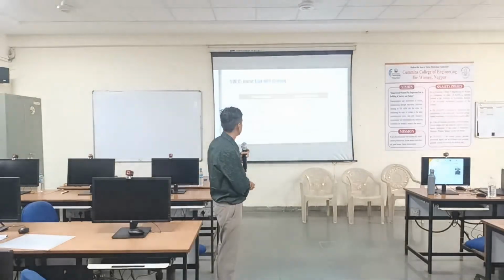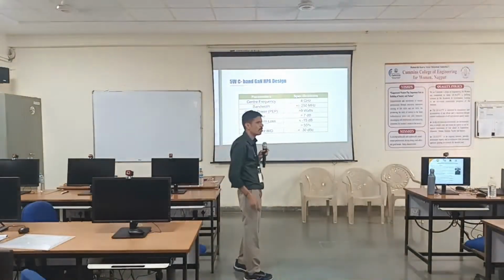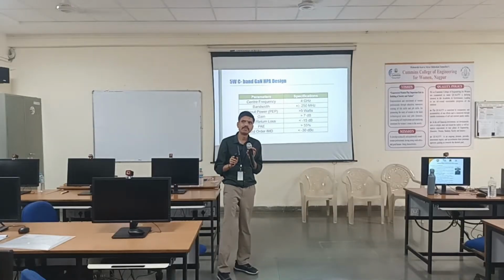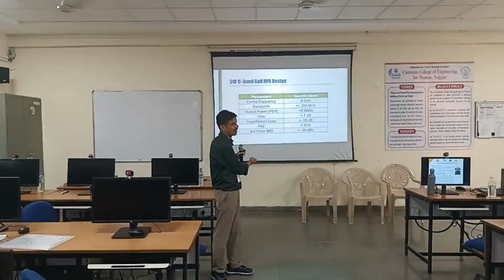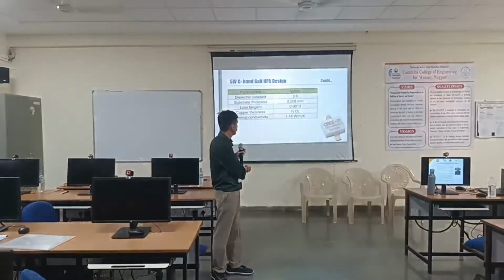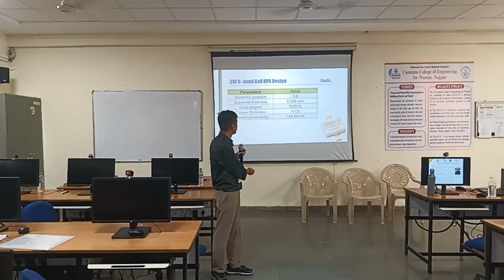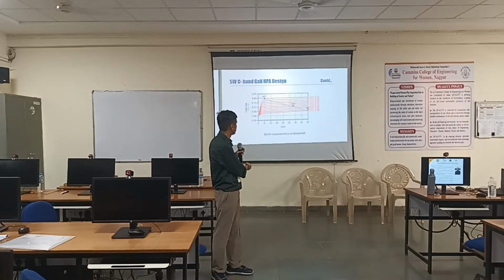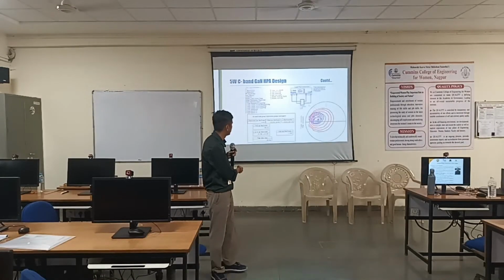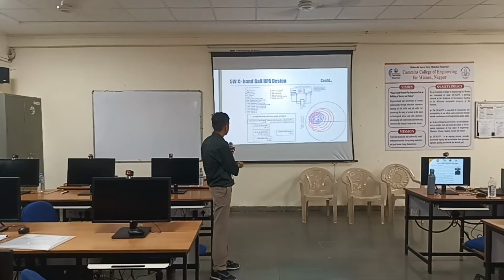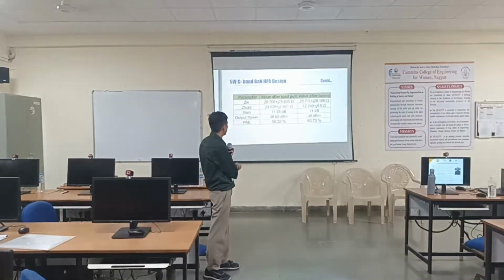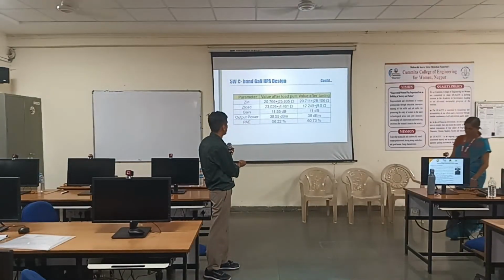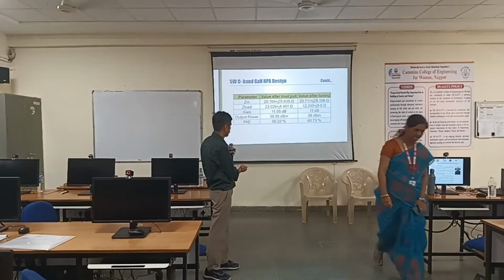Second design, more or less same, but the design will become simpler as you are operating at lower frequency, 4 gigahertz C band. So quickly I will go through this. This is the device which I have used. The same steps: DC line, operating point, stability analysis, load pull, getting these numbers. Similar job. Then translate it to some tuning values with some compromise in gain, output power, and PAE.